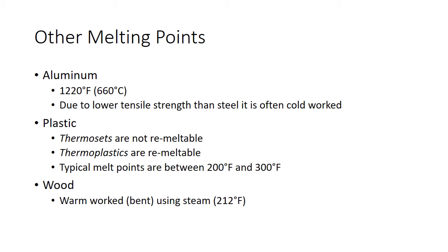And you can actually bend wood using a steam oven. It'd be a good senior project to build a steam vessel for bending wood and then bending the wood. Shove wood in, steam it up for a few hours, bend it, and there you go.